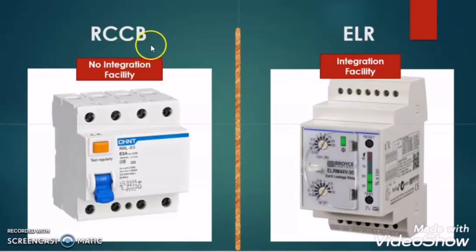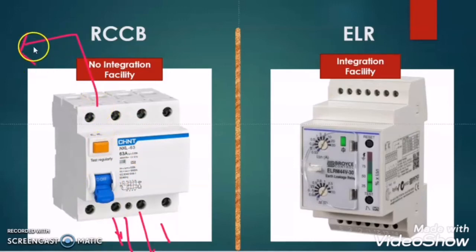The other difference between the RCCB and ELR is that the RCCB has no facility to integrate with other tripping circuits, but the ELR has this facility. What does it mean? Suppose the RCCB senses the fault and it trips itself. But with the help of this RCCB, we cannot give a command to another tripping device to trip.